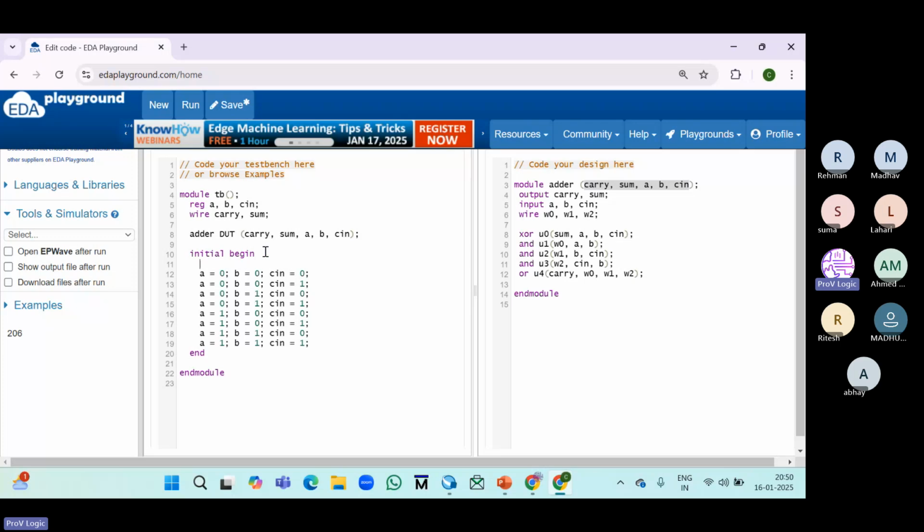Okay, so to display the statement in C language we use a printf. Scanf is used to scan the data whatever assigned previously. So after it scans the data, printf just displays the statement. So in Verilog HDL we use system tasks, or else we call them simulator directives, like $display, $monitor, $strobe, and $write. There are different simulator directives. So one by one you will understand the difference.